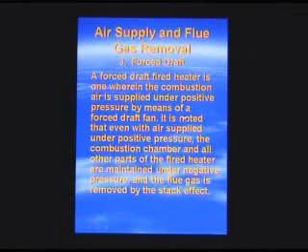Forced draft unit. In this case, we will use a combustion air blower, a forced draft fan, to bring air into the burner. However, the pressure drop across the burner is such that the combustion chamber can still operate very close to ambient. Actually, in some cases it can be slightly above ambient, but generally it's below ambient. So most of the pressure drop has occurred across the burner.